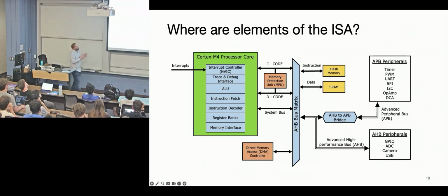I think the big idea of this class, of what you should be getting your head around with memory mapped I/O, is that you have a core and you have peripherals. Remember, peripherals are just locations in memory from the point of view of the core. But there's a mechanism by which we have to interact with those things. The core talks to the APB bridge.